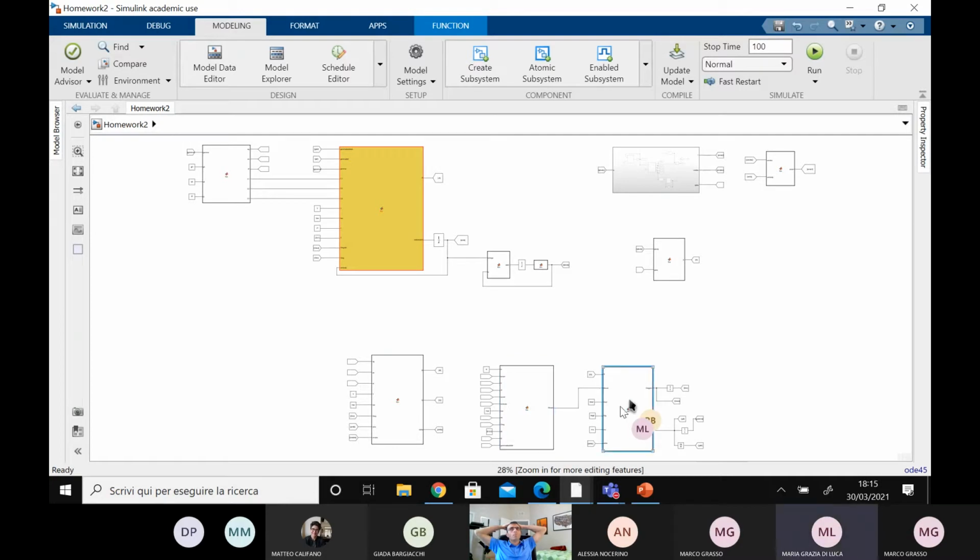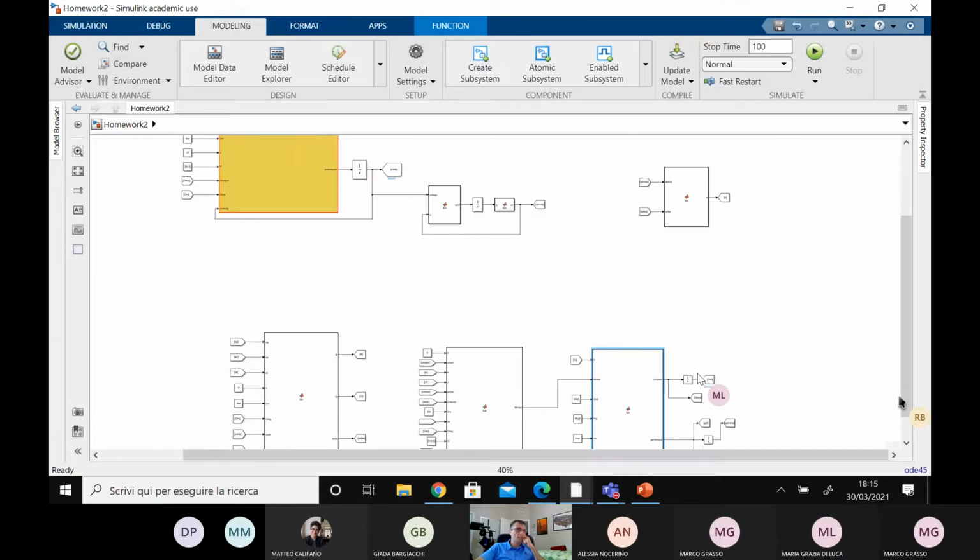Right. So, I simply have a memory block. In my case, I output just the eta and then I use it somewhere else. But I do have a simple memory block in front of eta before it's used somewhere else, and that solves the problem. It breaks the algebraic loop. It gives it a 0,